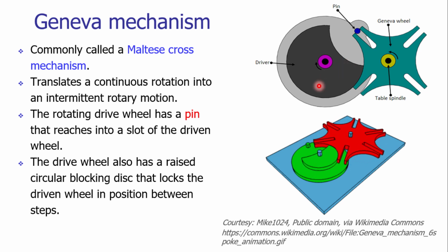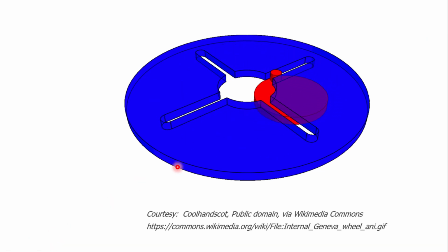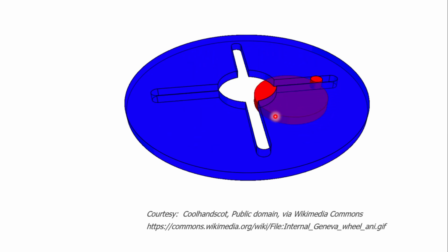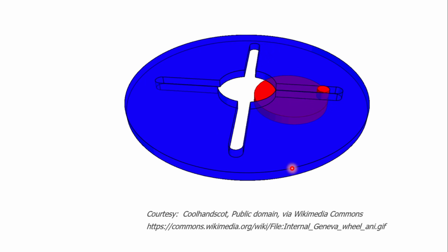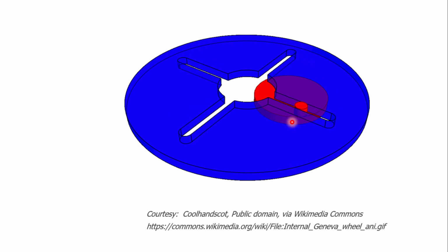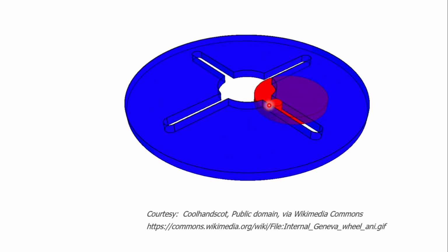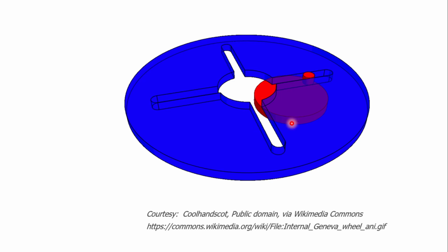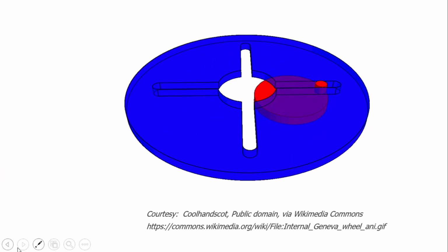That is not true in the internal Geneva mechanism. This particular angle would be more than 180 degrees. Now here you can see the engagement has been done, and the disc has to rotate more than 180 degrees to have the disengagement of the pin from the slot. You notice the pin is engaged here and it is getting disengaged at this particular point. So from engagement up to disengagement, that angle is more than 180 degrees. This should be noted.